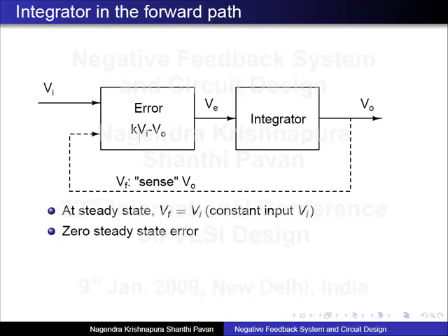Okay. What is the input? It's some input voltage Vi. The desired output is some K times that. And we have to compare this K times the input, KVi, and the actual output V0. This gives me the error. And this error I have to integrate.